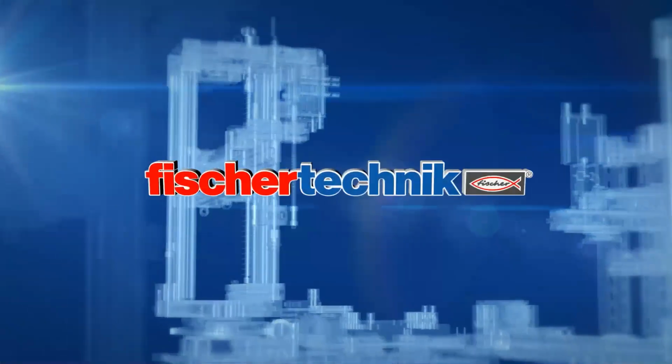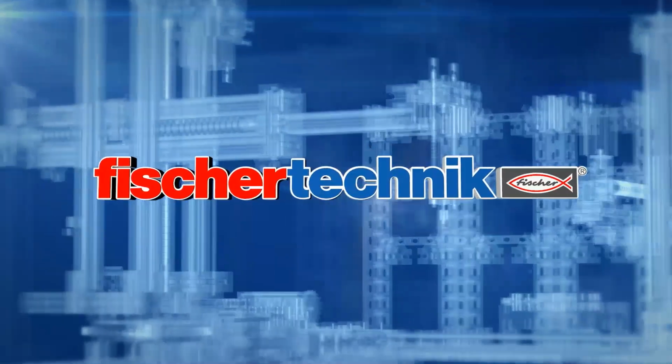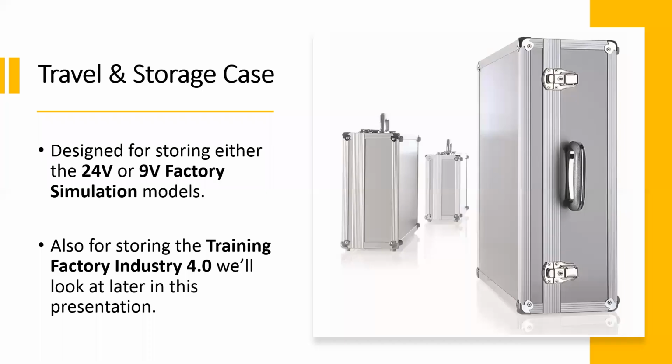Again, each station on the 24-volt version has a relay board for motor polarity reversal and both a multi-pin connector, 26 pins with a grid of 2.54 millimeters, as well as additional PCB terminals with pushing connections for all inputs and outputs. Now, before we move on to the next group of models, I do want to mention that there is a storage option available for those users of either of the 2 factory simulations we've just discussed who may need to transport the model or who wish to protect it when not in use.